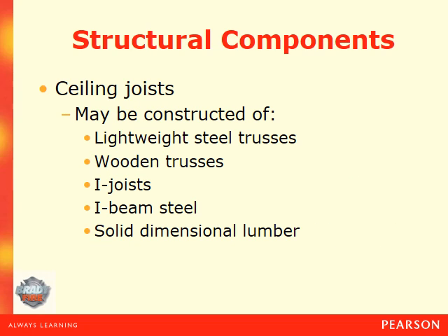The ceiling joist may be constructed of lightweight steel trusses, wooden trusses, I-joist, or I-beam steel, or some sort of solid dimensional lumber. And a lot of this comes down to what age the house was built. The older the structure is, the more likely it was made of that solid dimensional lumber, as opposed to the newer it is, then you get that lightweight truss type design.